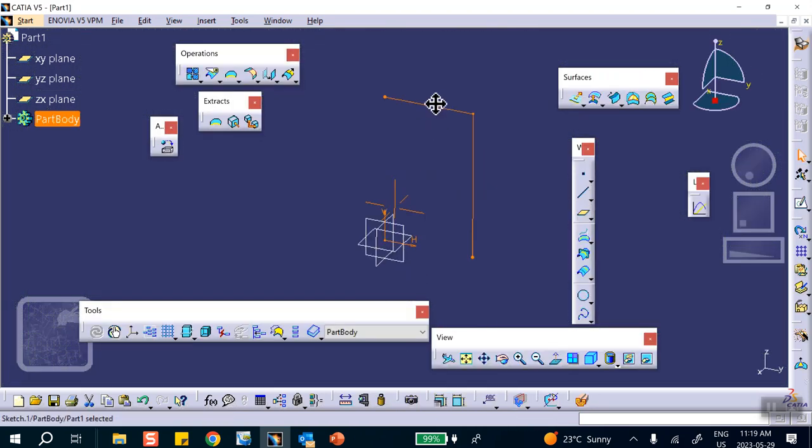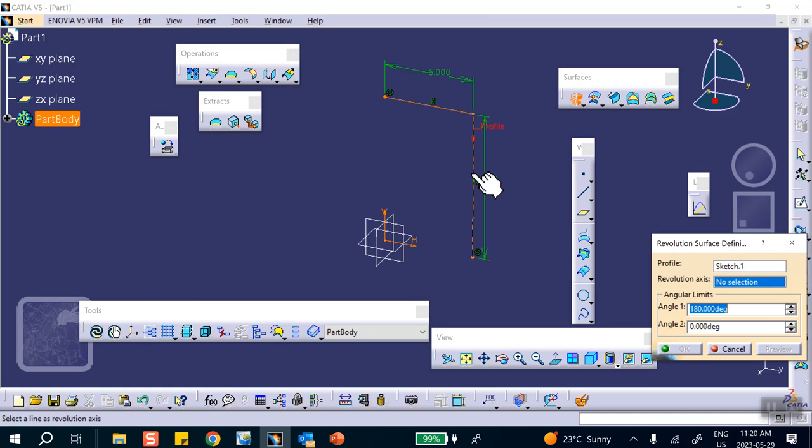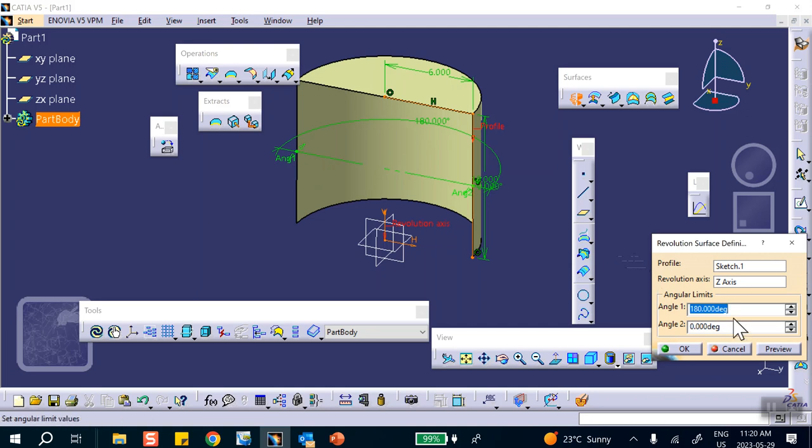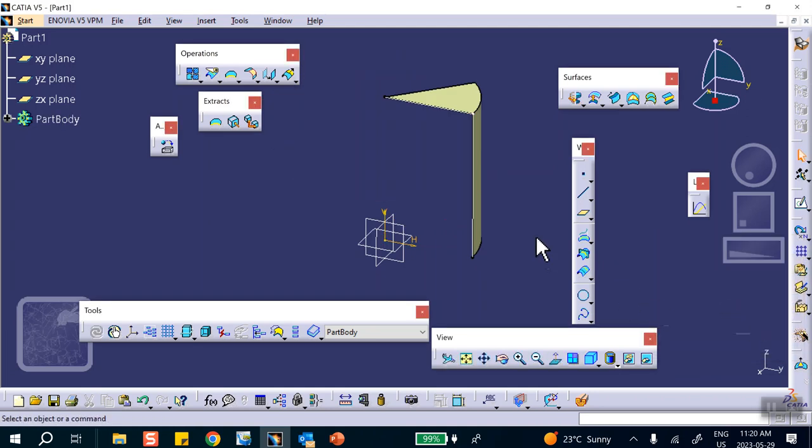And we're going to revolve this thing. Now remember, we're trying to create a surface, and this is the main toolbar for creating surfaces. This one on the left is extrude, revolve, and some basic primitives here. So I could have done this with this cylinder, right there. But I'll revolve it. This is the sketch, and I'm going to revolve it about the z-axis by 45 degrees. Okay, there we are.